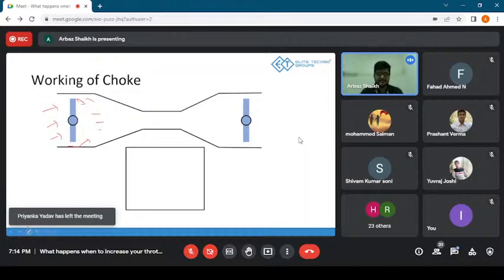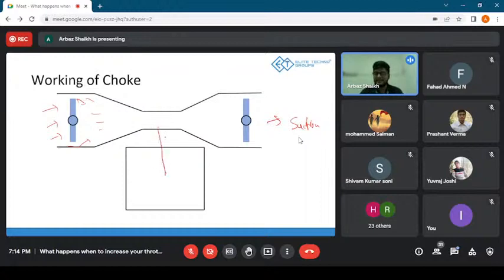And because again, if I draw the suction pressure once again from here, which is coming from the engine side, and if very less amount of air is entering over here, all that air should be compensated by the fuel. It would go something like this, right? So more amount of fuel would come out. And instead of our stoichiometric ratio, there would be more fuel going inside the engine when compared to the air. Only very few molecules of air would go in when compared to our stoichiometric ratio.